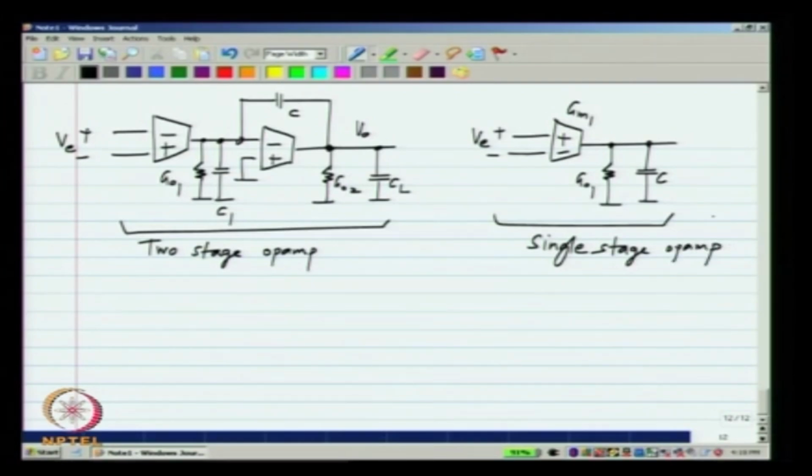And in each of these cases we could use voltage buffers after these op amps, but like I mentioned earlier, voltage buffers are harder to make in these CMOS technologies, especially with low supply voltages. So, we typically tend to use these op amps without explicit buffers. These things will become clearer when we come to circuit realization of these op amps.